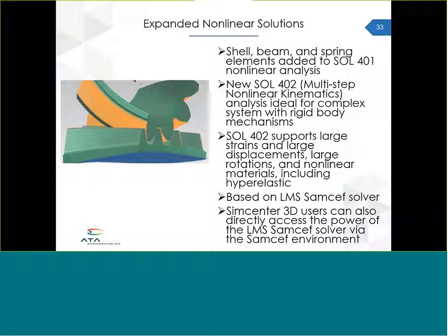SOL 402 also supports large strains and large displacements, large rotations, and nonlinear materials, including hyperelastic. And it is based on the powerful LMS Samcef solver. So SimCenter 3D users can also directly access the power of the LMS Samcef solver via the Samcef environment.